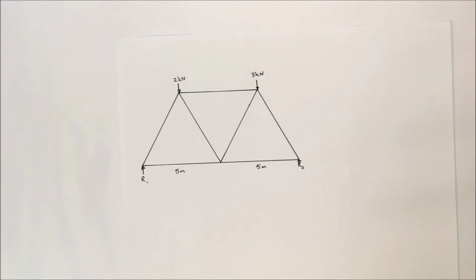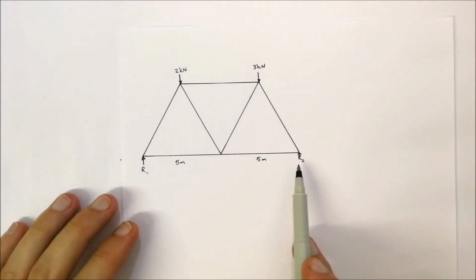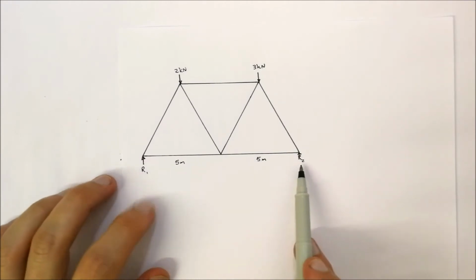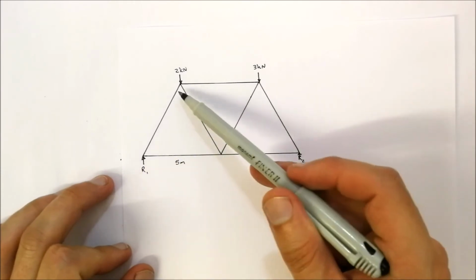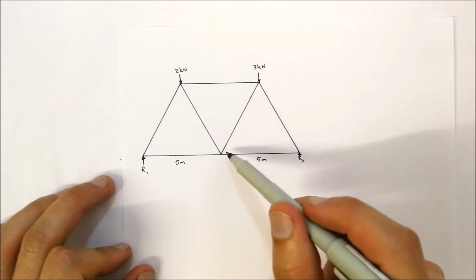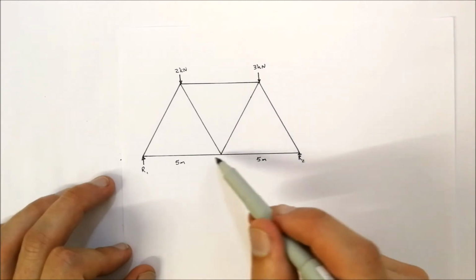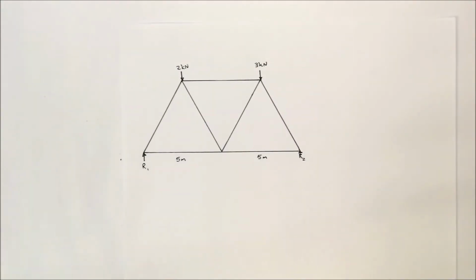So we've got this example over here. We've got a beam going across, like we've seen before. We've got two supports, R1 and R2. We've got diagonal beams, and this is an equilateral triangle, so 60 degrees for those angles. Very similar structure as you would maybe have for a house roof, going up at 60 degrees, and these are the supporting beams inside of it.